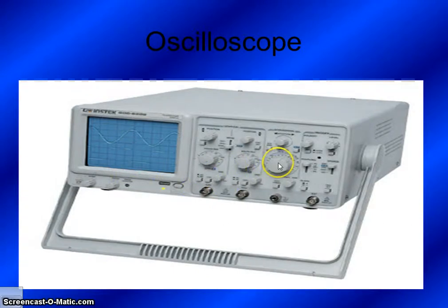Now over here we have our time. Let's say it's in seconds. What you would do is you are measuring a wavelength. Let's just say that it was 1 second per division. And you count them, so let's see what we have here. It's an easy way. I usually look to see where my lines are crossing. So here it looks like this is a good one. So that would be 1 box, 2, 3, 4, 5. So that means that the period of this would be 5 seconds. Remember what I said, it was 1 second per box. You got 5 boxes, so it would be 5 seconds.